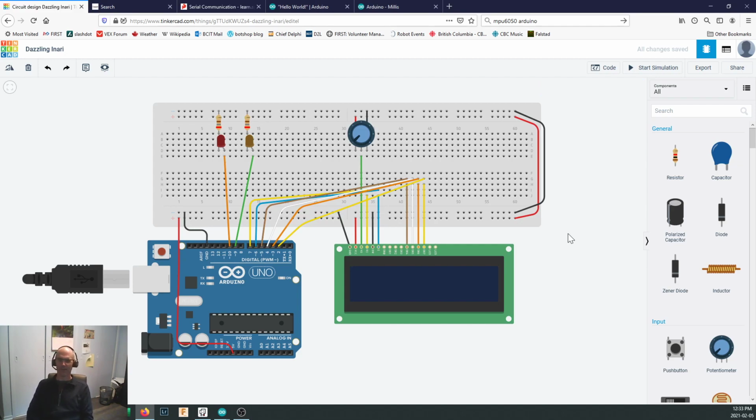Oh, that's a lot of wiring. Okay, but we've kept it in the same color that we're going to be using on our big bad breadboard when we do it for real. Now, yes, it was a lot of wiring, and that's because this is what we call a parallel interface. Instead of a serial interface where you've got one wire carrying all the data and the bits traveling along behind each other, in this case, we have 4 bits of parallel data.